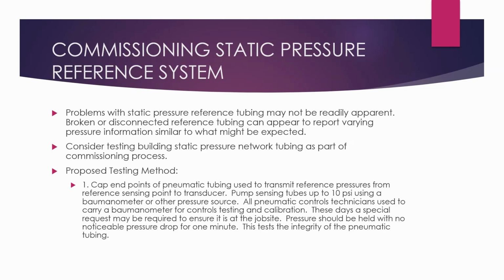We spent several months arguing, between myself and the client rep, about what the problem was with this building static pressure, and lo and behold, they had not piped the building static pressure all the way out to the exterior of the building.